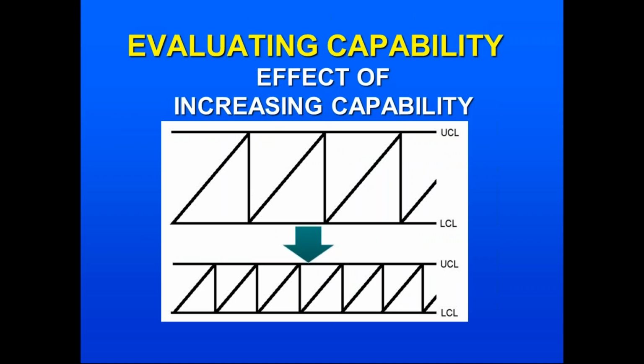The problem is if you want to go any higher than that, you'll be compressing your control limits. When you compress your control limits, you have to make more and more adjustments, which means more and more operator intervention, which is not what you want to do. And there is no economic benefit for doing so. Now, sometimes there's a benefit. For example, I had a situation where the customer says the mating parts are a problem. Can you control your process tighter for a period of time to help us out? I said, well, yeah, you can. You will have to do more adjustment, but at least now you have a reason to do so. If you don't have a compelling reason, it's not in your best interest to compress your control limits.